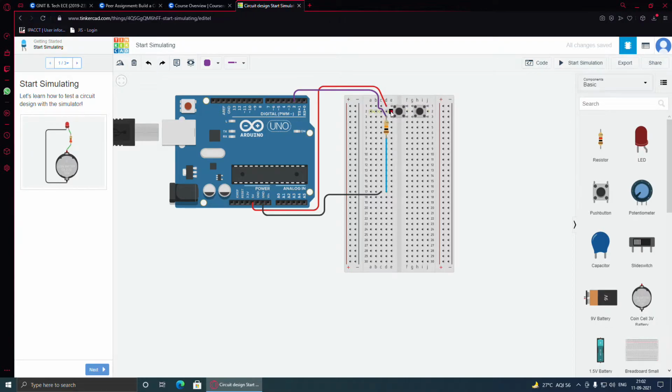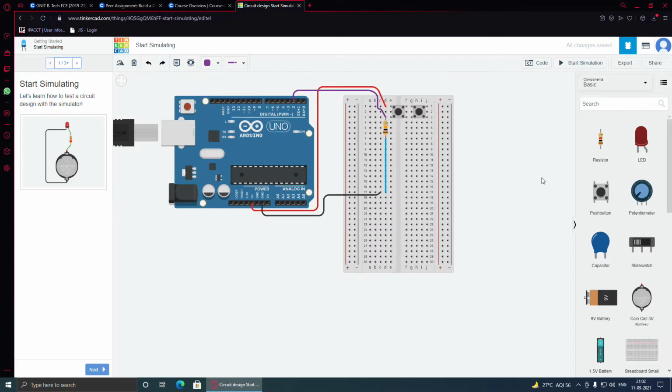Before that, I'll explain the basics of the push button. So the push button, as you can see, is quite simple. It acts as a switch. Clicking it completes the circuit or performs some action, and releasing it opens the circuit. As you can see visibly, it has four terminals, but it doesn't really have four terminals. It has two terminals, because this terminal and this terminal are internally connected. Similarly, this terminal and this terminal are internally connected. So we have to use either of the two sides.